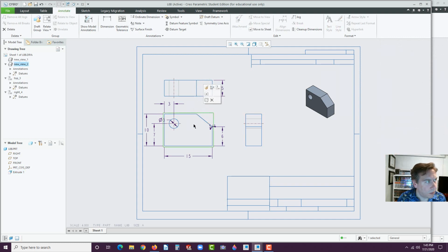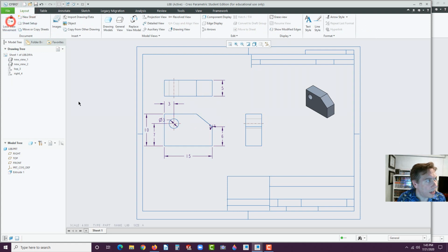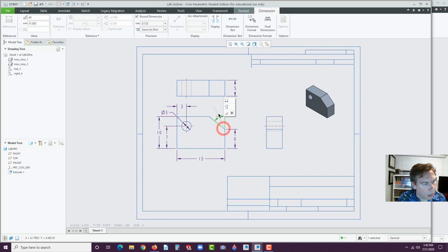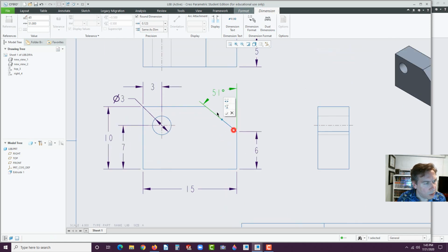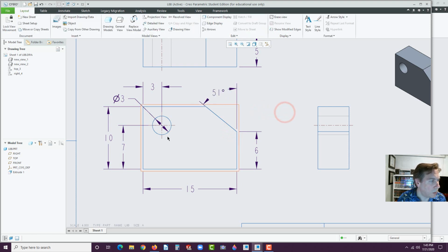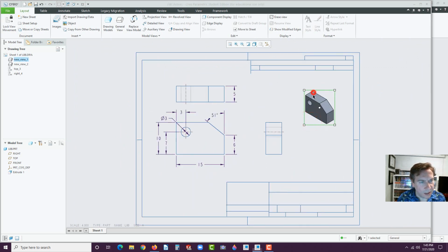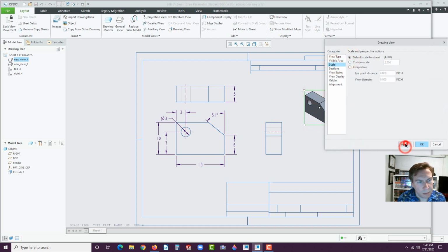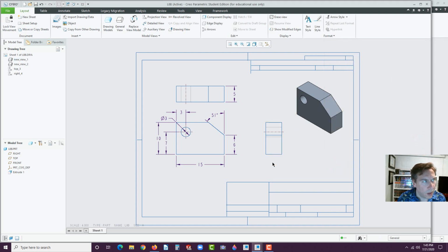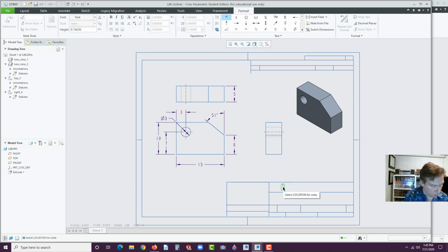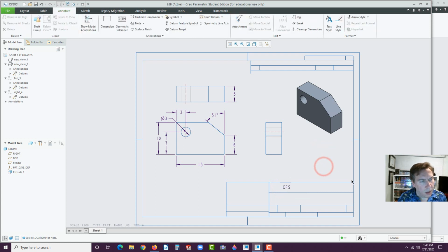Now let's just move it, and remember to move it, you have to go to Layout and turn off lock view movement. Then you could click and drag this over, make more room, and make any modifications to the dimensions, put them where you think they're going to look best. And you can also grab the ball there to help you take them off the edges. And I should have actually probably just left this to the regular scale, so I'm going to use default. And then just put your name. Go to annotate, note, all right, and that